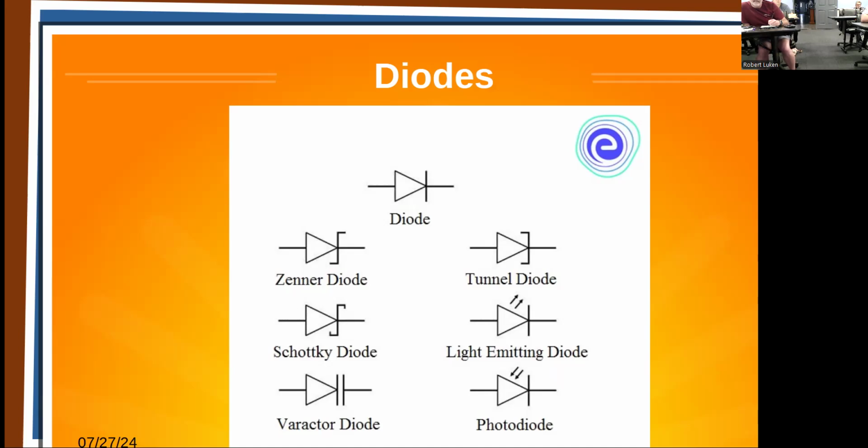It turns out all diodes generate light. At the p-n junction, as the electrons recombine, they release energy, and that energy can be in the form of light. It depends on the amount of energy, and that determines the frequency. So they just learn how to enhance that effect. In most cases, the diode is in a package where it doesn't let the light out, whereas a light emitting diode is in a clear package or a colored package.